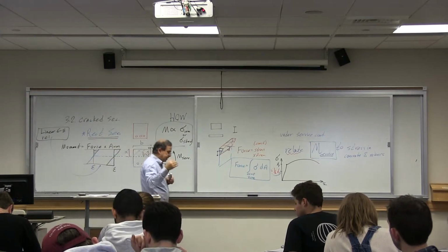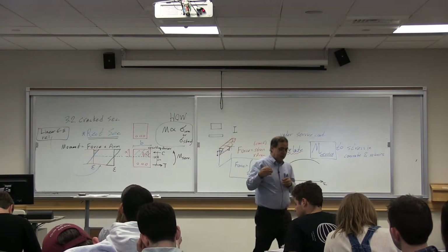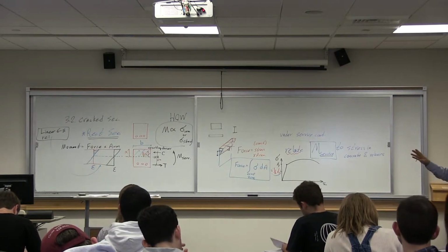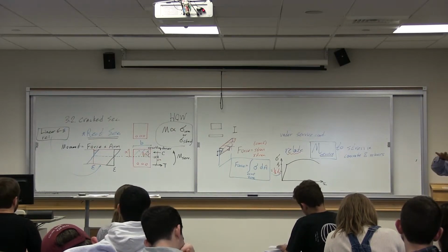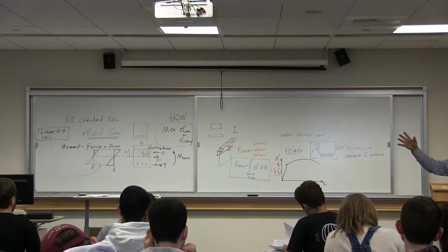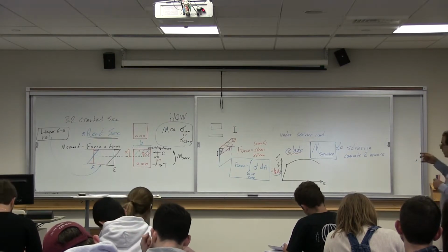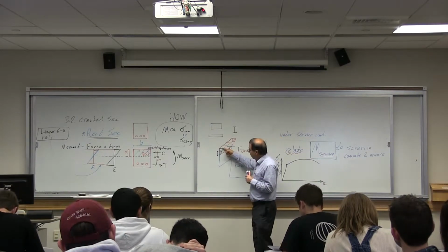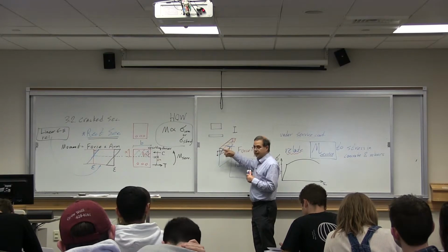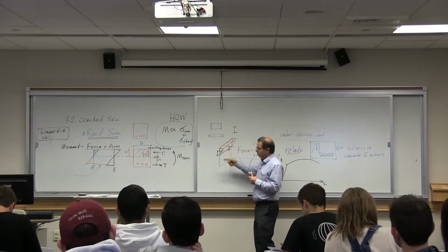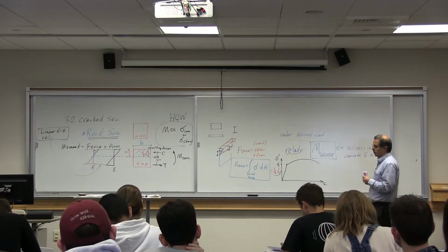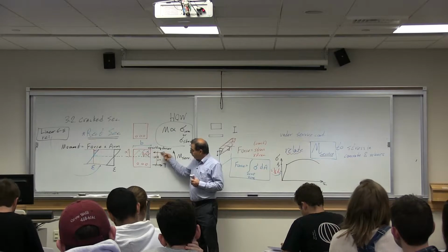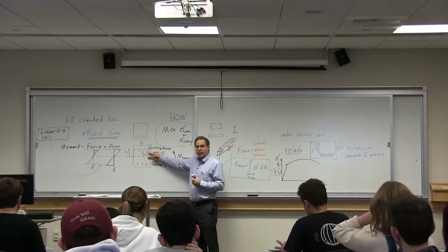So where is the resulting compressive force? In order to find the resulting compressive force, the only way mathematically you can do it is to integrate stress over the area. But as we just discussed, the result of this integral and looking at this triangle is the same in terms of the location of the resulting force. Therefore, as you said, the compressive force will be applied at 2/3 of the height.